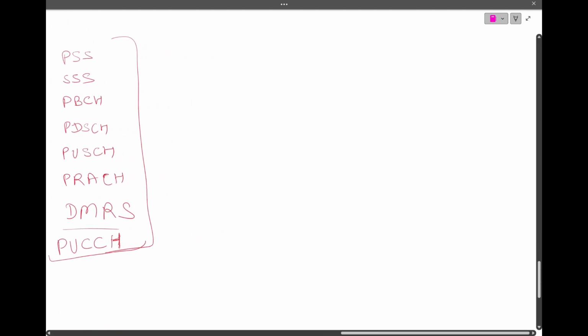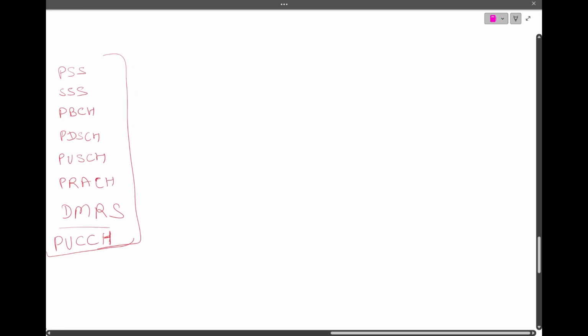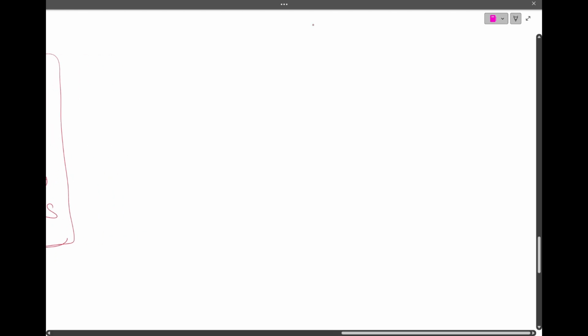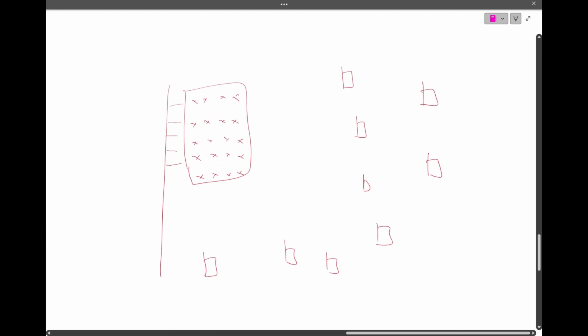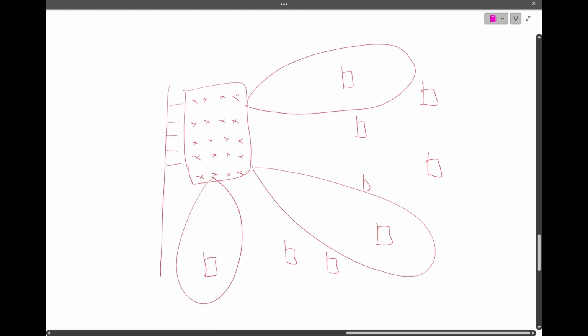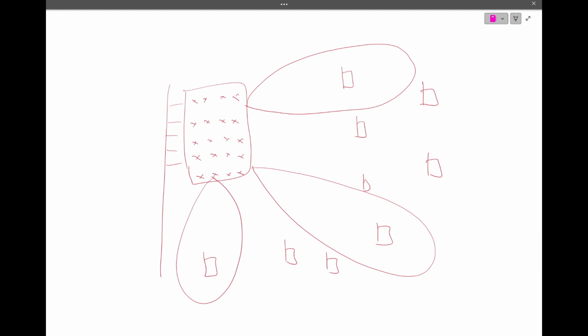Now in 5G we can do better. We can optimize this whole process further. That means we can use many antennas, both at the transmitter and receiver, both at the base station and at the UE. We can do parallel data transmission. We need not have only one antenna, one layer kind of data transmission. By using multiple antennas, we can also direct our signal towards a particular UE. That means we can form a beam towards this UE when you want to send data to this UE. We can do this, let's say here, or let's say here. This way we can optimize our signal transmission further.